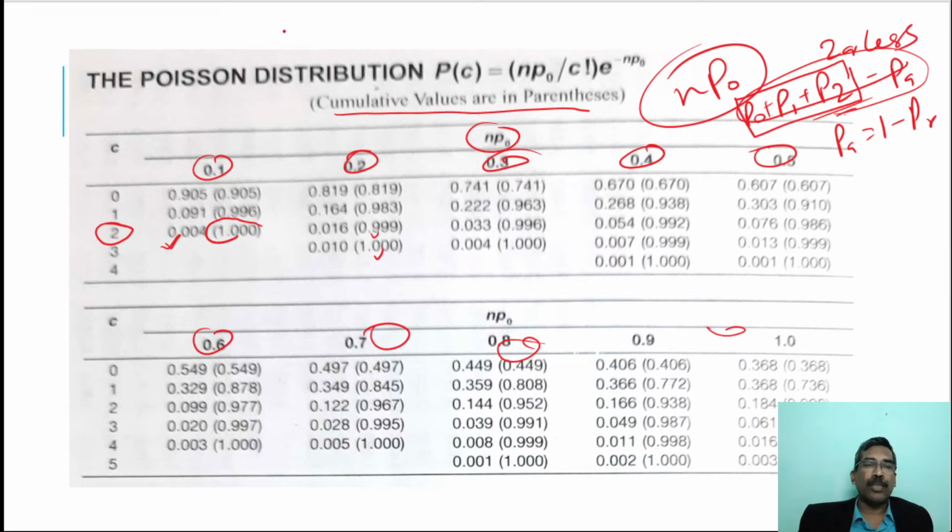If the probability of acceptance is indicated as 1, and you want to find exactly 2 defectives, then in that case we can take the outside value. This is the absolute value. Absolute value means the probability that in this sample there will be exactly 2 defectives. If we ask what is the probability that the number of defectives will be 2 or less than 2, then for the PA value we should take this bracket term value.